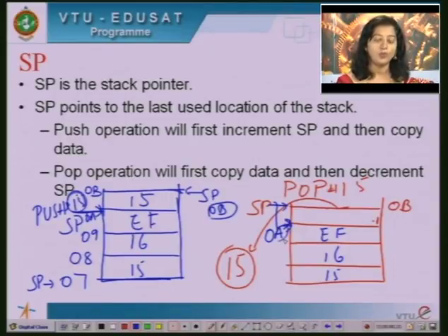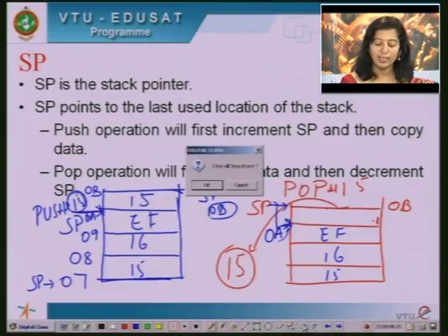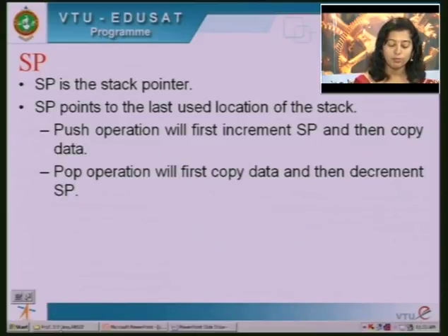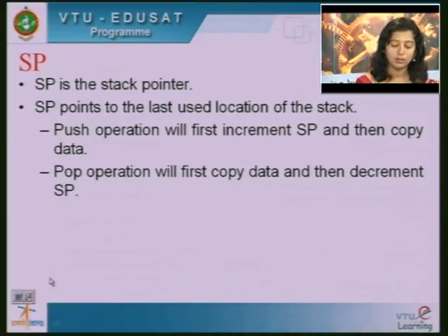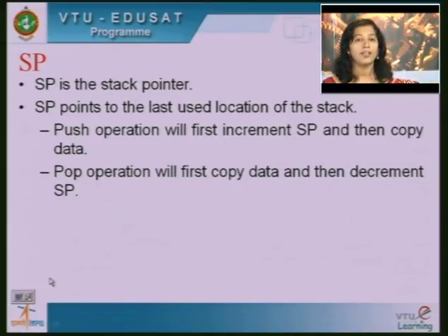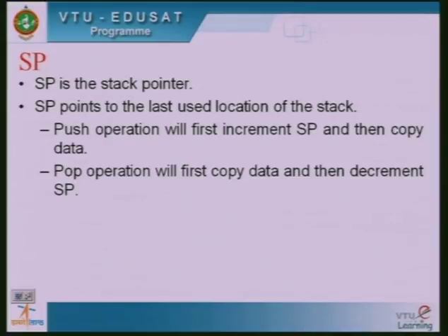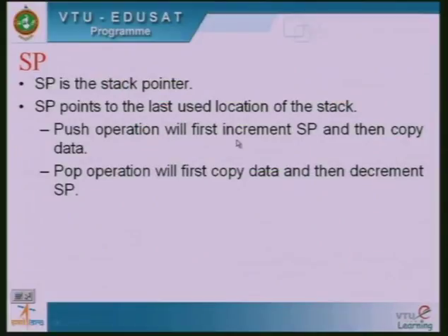So as I told you, stack operations are very important and they are normally used with any microcontroller or even a microprocessor. As mentioned here, push operation will first increment the stack pointer and then copy the data onto the stack.